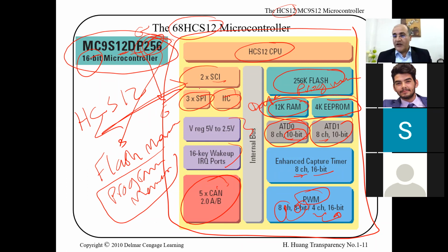Like FlexRay. FlexRay, for example, is a network protocol. If you want to compare, CAN can range its speed up to 1 or 2 megabits per second, and its bus can go up to 130 meters, with up to 100 controllers communicating with each other, message-based.